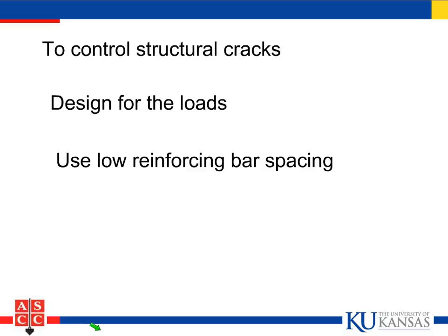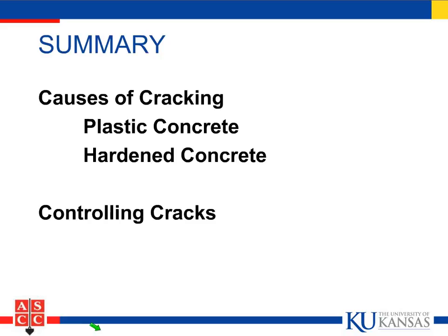So to control structural cracks, we need to design for the loads, and we need to use low reinforcing bar spacing. Okay, so that brings us to the end. We talked about the causes of cracking in both plastic and hardened concrete. We talked about controlling cracks.